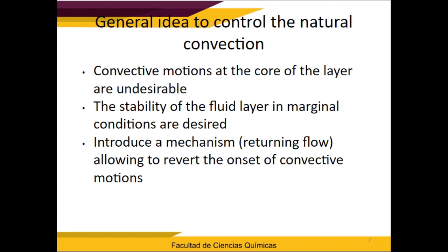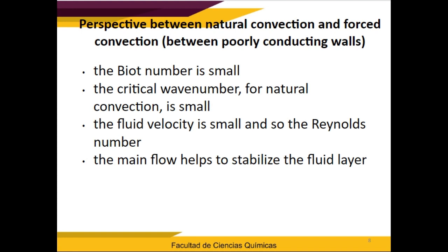What is behind this is that you need to monitor the temperature gradient across the fluid layer so that the Rayleigh number can be estimated so that a decision on top wall motion could be made. Here are some notes about the natural and forced convection for a better understanding on how this possible solution works. These details will also help you to have a picture of the conditions maintained in the elongated cavity.